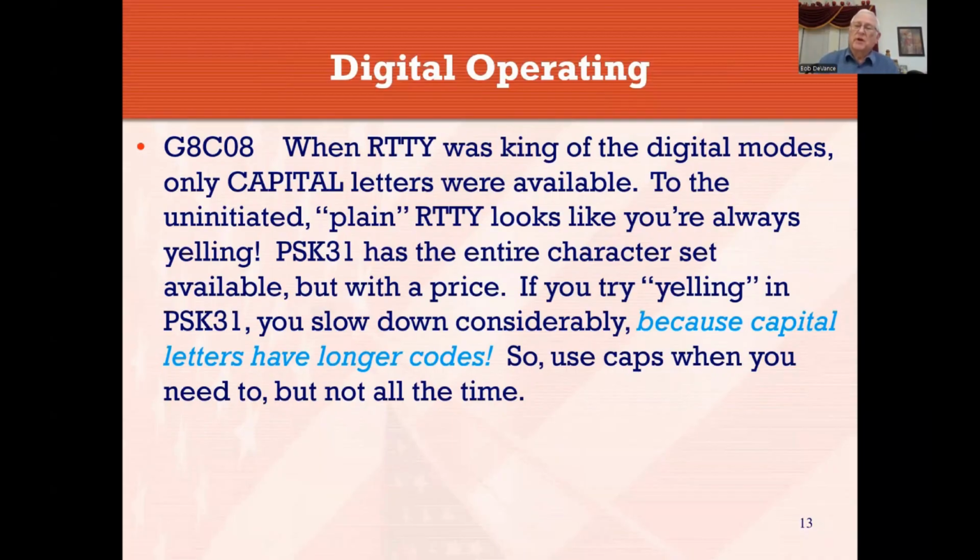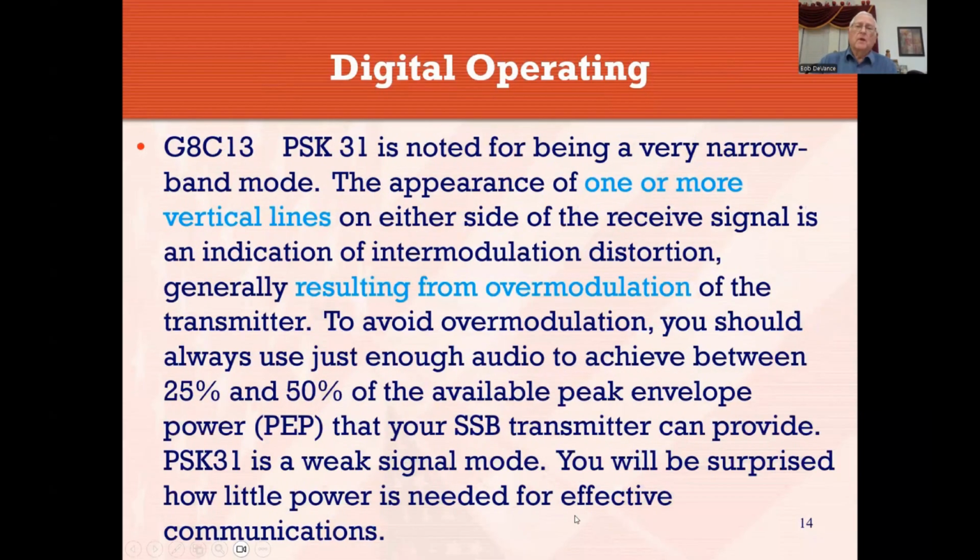But when we switch over to the alternate character set and get away from the all caps, then it slows things down. Use caps when you need to, but not all the time in RTTY. Back to PSK 31, it's a very narrow band mode. It uses 31.25 hertz. I mean, it is really, really a narrow band mode.